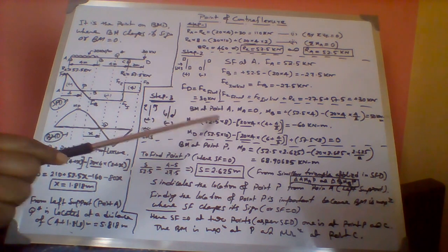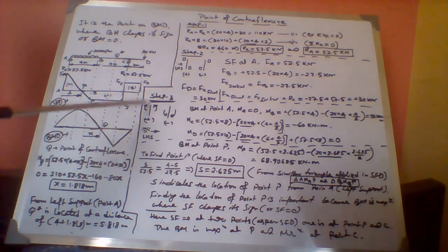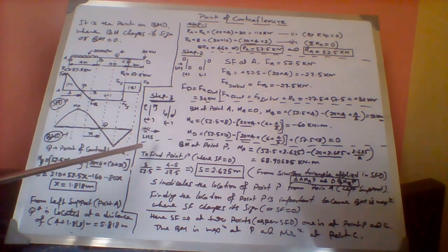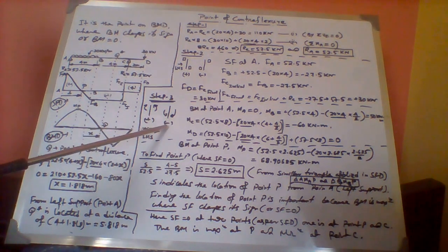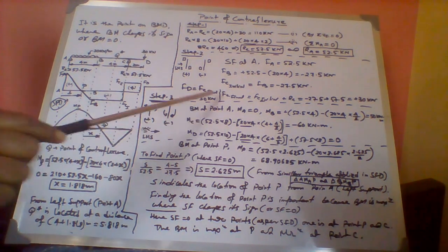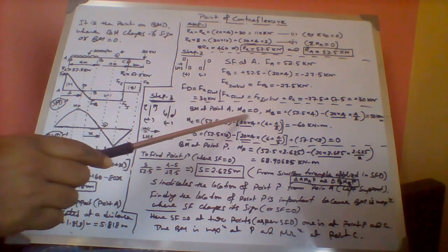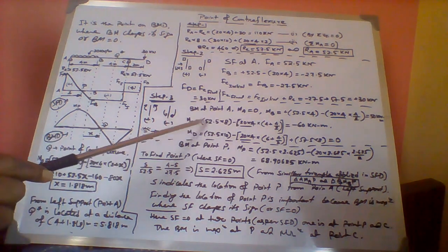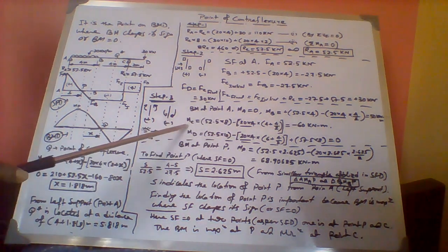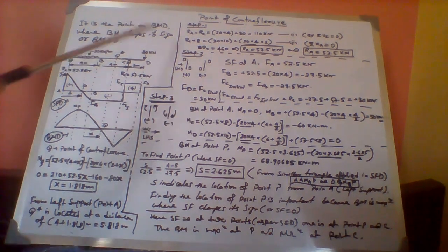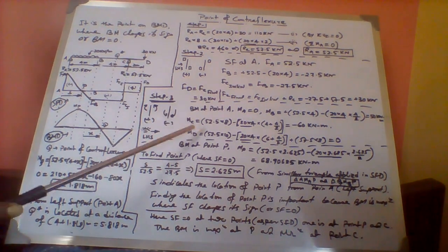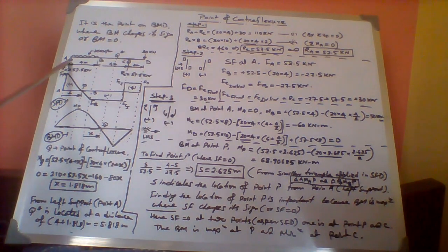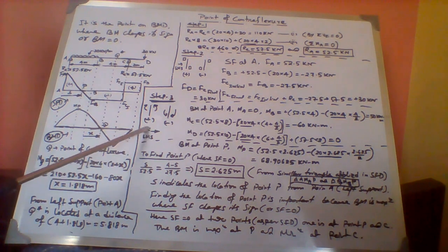So try to find out the bending moment. Before that, first draw the sign conventions. As we know, this is plus, this is minus. So by applying this, we can find the moment at A, moment at B, moment at C. I'll just indicate one moment, that is moment at C. If we want to calculate the moment at that point, we can write moment at C equal to this force multiplied by that distance, moving clockwise, looking from the left.